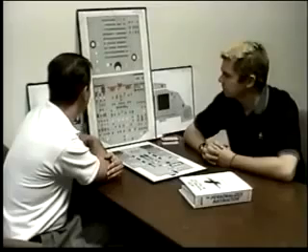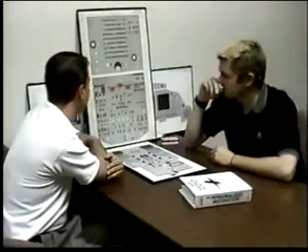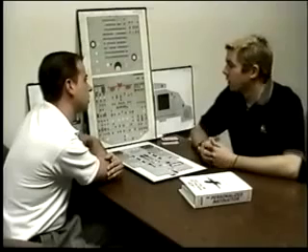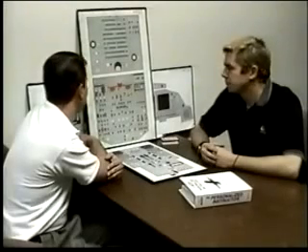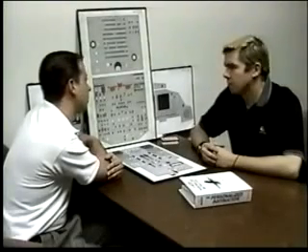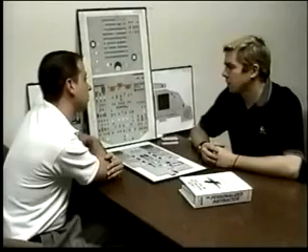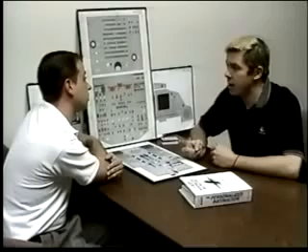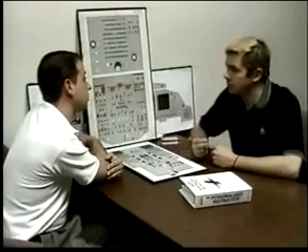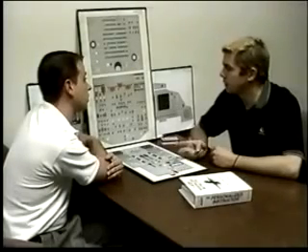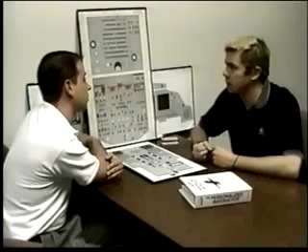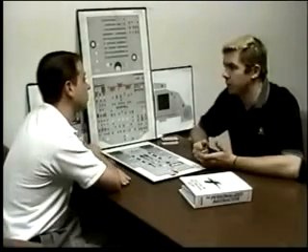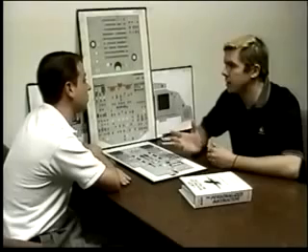Let's cover emergency electrical configuration. First, how do you enter emergency electrical configuration? With a loss of AC bus 1 and 2. Okay, what do you have available while the RAT's being deployed? During the RAT deployment, there's 5 seconds in there where you only have 2 batteries and 2 buses and 2 displays. The 2 buses are the essential AC bus and the essential DC bus. You don't have the sheds. Because of that, you only have the captain's PFD and the upper ECAM.